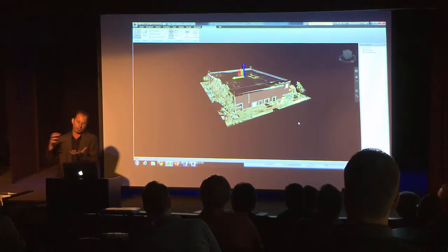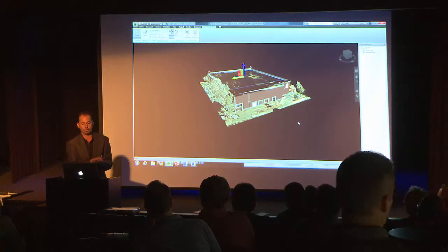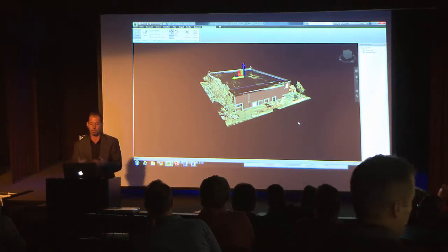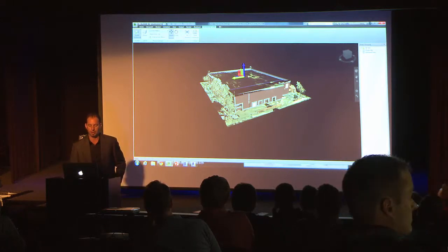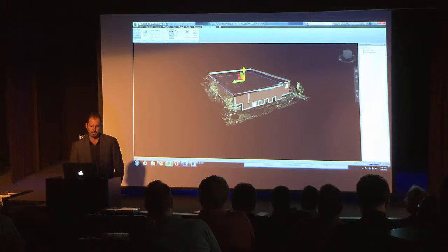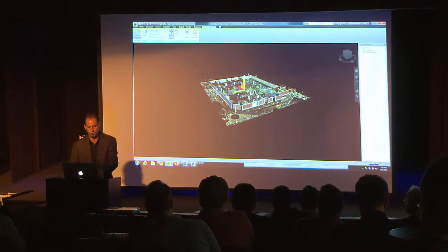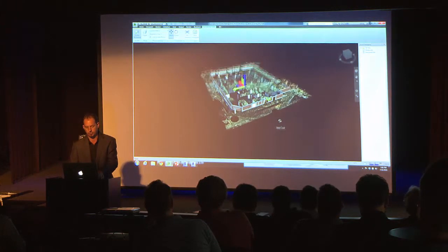You take your Revit model, you bring that inside as well, and then you can do a construction verification to make sure maybe the building was actually built that way and you want to compare it to the scan data. Maybe you're just using the scan data to compare that you didn't miss anything during the Revit modeling. Either way, you can go in and create sections of the data once you bring it in. All right, so it's a true section through the Revit model as well as the scan data.